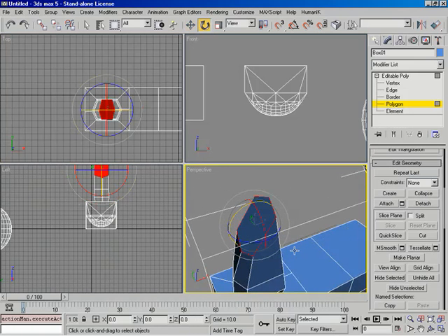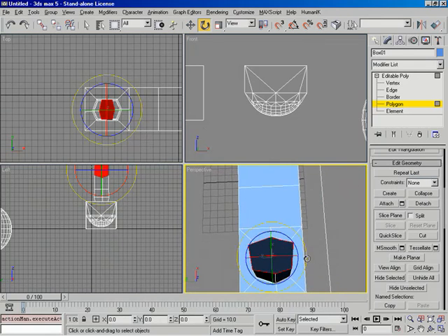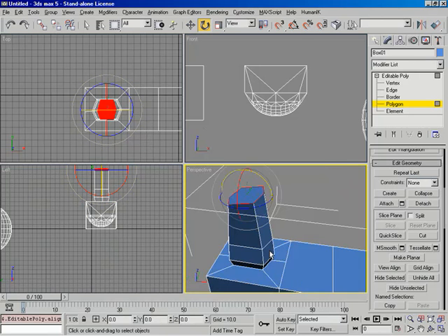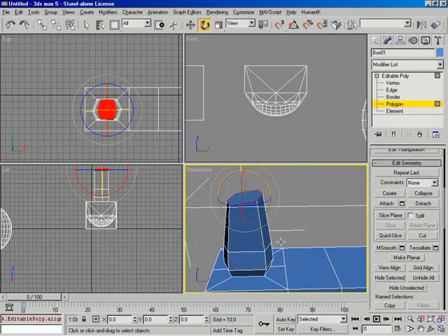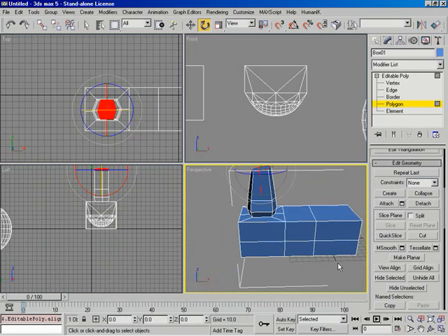Right. And now, of course, let's undo that, excuse me, and I come up here, if I use my perspective mode and do view align, look what happened. It's actually going to take those vertices and rotate them to match the perspective view. Exactly. You can see how it's rotated it right there. Okay, very cool. So grid align is basically the same thing except we're dealing with our grid at the bottom. And in perspective mode, it will actually translate those vertices, as opposed to rotating. Right.